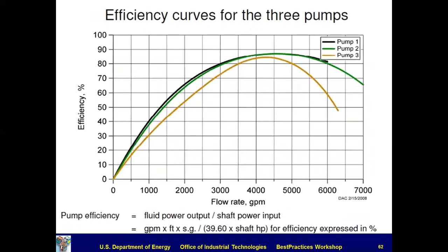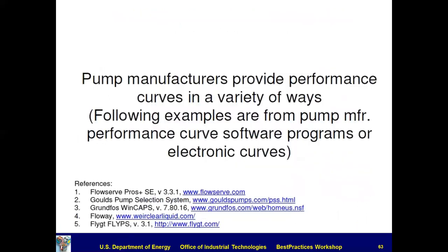There are our efficiency curves for three different pumps. So if you know a flow rate, you can read up and over to the curve and determine your pump efficiency. Okay, pump manufacturers provide performance curves in a variety of ways, so I have some examples here of what some of those might look like.